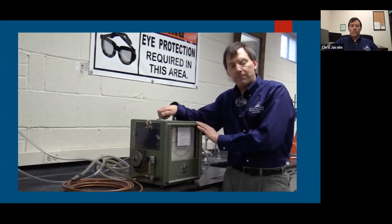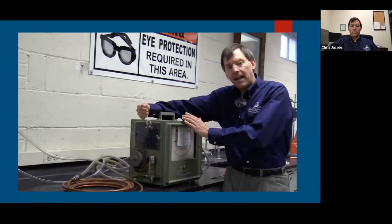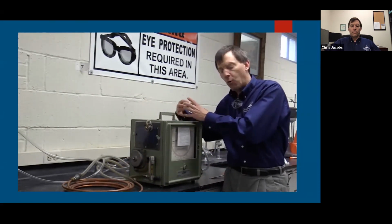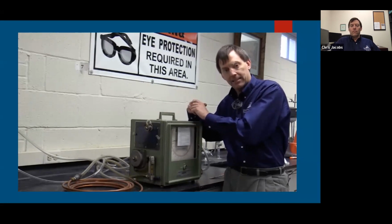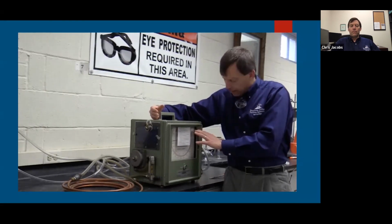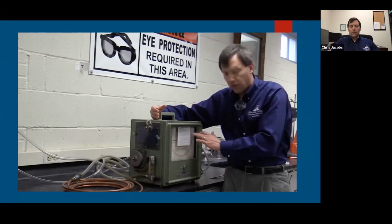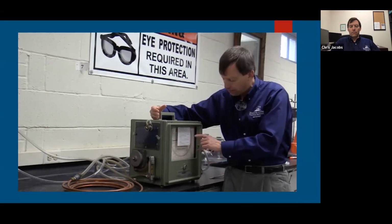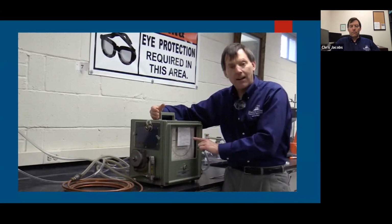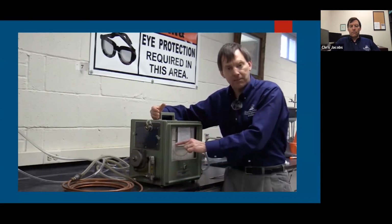Now, two things I want to mention about this. Number 1, when you first turn it on, remember the gas has to purge the air that was in that measuring chamber before it can start analyzing the gas itself. So it may take a few seconds for the needle to drop from 1. In this case, we're using the inner scale, the red scale here. This is the one for gas with a specific gravity of less than 1. It may take a few seconds for it to come down to say 0.95 as it starts to purge the air out. And then it will fairly quickly move around to approximately the specific gravity.